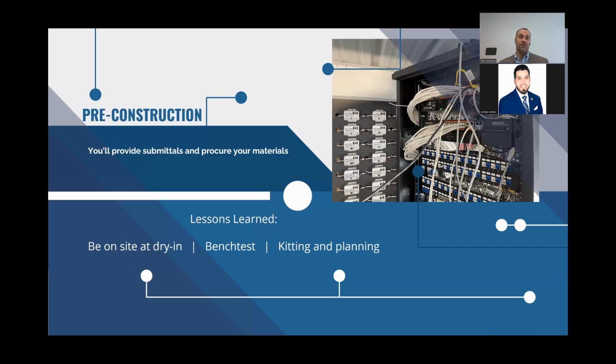But ideally, at best, you don't want a hammer-wielding guy swinging a hammer near your $1,000 switch and blowing drywall dust into the motors and the fans. So have a door on the IDF or the server room, get it locked, make sure they sweep and clean it, and then get in and start doing your wiring and pulls, because your lights will have to be in either as the ceiling goes up or before they put the ceiling in. You're going to want to get your wiring done before that.